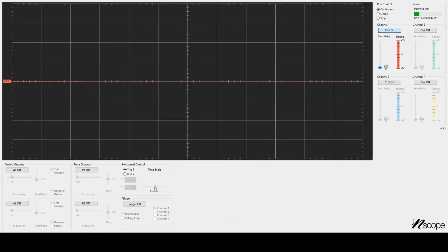Okay, we're back to, say, 5 milliseconds, and we'll turn trigger on. I'm going to move it up to 2 volts. And I've pushed the discharge button, so I know my voltage is 0. Now I'm going to push my charge button. And the scope waited to save data until the red line went through that intersection to show me this plot.